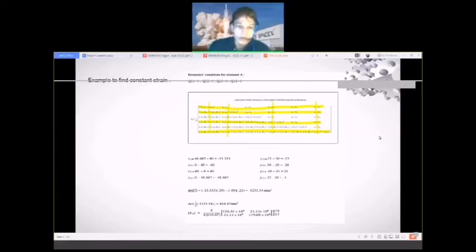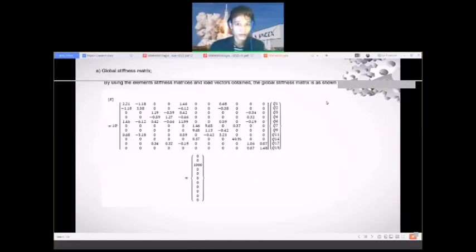Then we need to find X13, X23 by using the displacement given by the Ansys in question 2. So we just find the values, then we find the delta J, find the area, and we get the strain stiffness. So between the 12 elements, we get the stiffness matrices. So we combine them to be a global stiffness matrix. So this is the value.